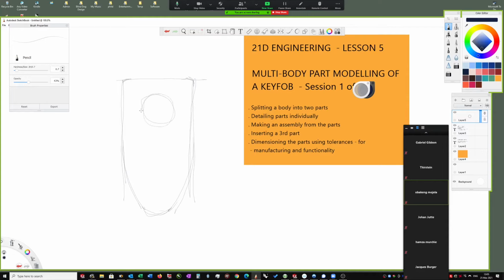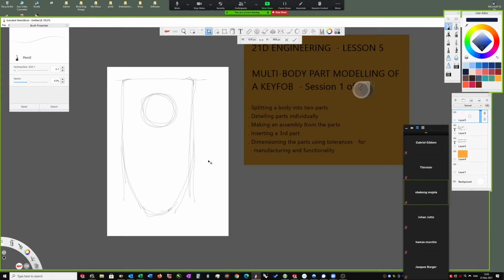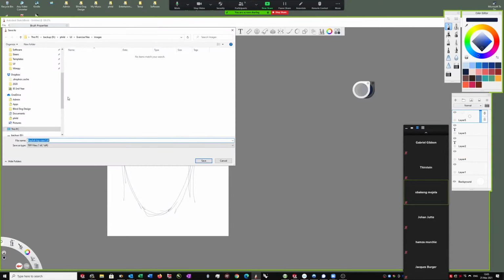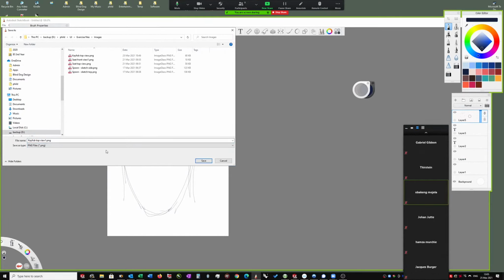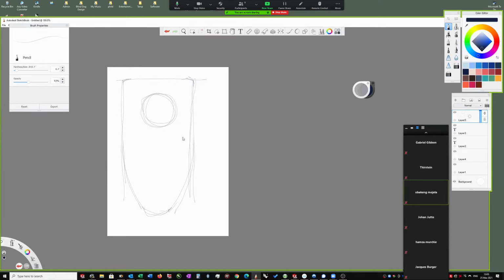And then we're going to put a round button in the middle. Okay, and that's what I'm doing. I'm not going to get fussy about the sketch. I'm going to snip that out and quickly save it. Now you need to save it. If you're going to use it in SolidWorks, you need to save it as a PNG or a JPEG. I'm going to replace my existing sketch. TIFF files won't work. Alright, so that's this program's function done for now.